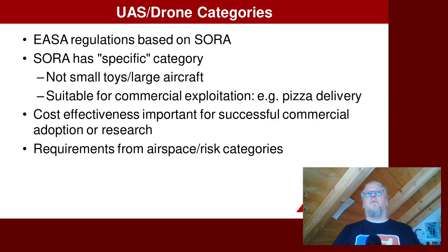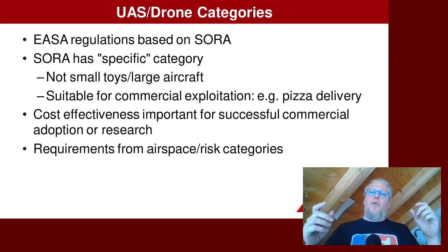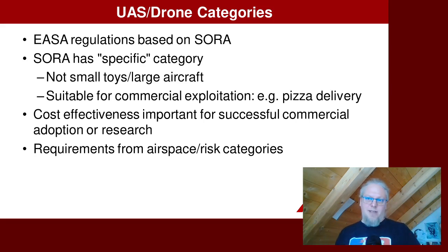Lastly, the EASA concepts also include the U-space concept of operations. That's the replacement for air traffic management for these mid-sized drones, and it also has to interoperate with ATM. And in here, we have different airspace categories or types. So flying over unpopulated woodland would be very low risk airspace, but populated city centers are, of course, much higher risk. And then at the highest risk, we have something like airports or nuclear power stations. And what we're really looking at is providing reliable command, control, and communications links for these mid-sized specific category drones for the highest airspace risk classes, because on the lower risk classes, you might not need that much reliability.